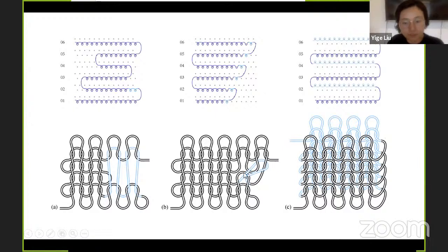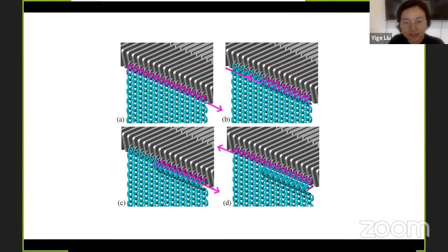If we split more knits, it will become too tight for knitting, so the yarns may break or cause other damage to the needles. So in my approach, I just use partial knitting by adding short rows to achieve this 3D geometry on the